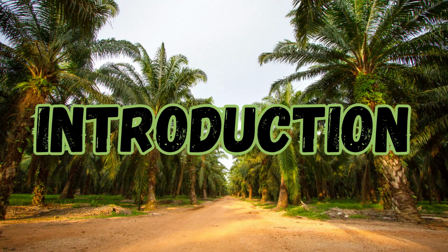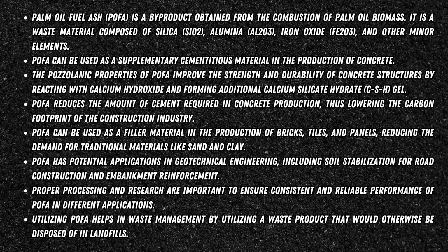The green material that we use is palm oil fuel ash, or what we call POFA. So let's move to the introduction. Palm oil fuel ash, or POFA, is a byproduct obtained from the combustion of palm oil biomass. It is a waste material composed of silica, alumina, iron oxide, and other minor elements. POFA can be used as a supplementary cementitious material in the production of concrete.